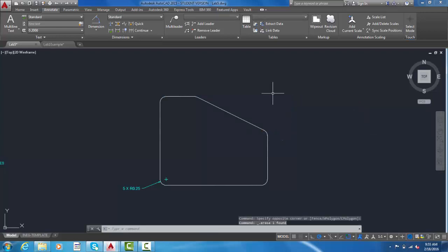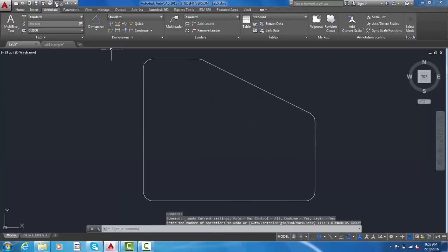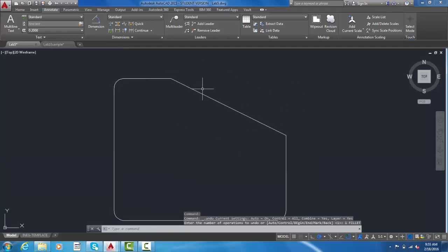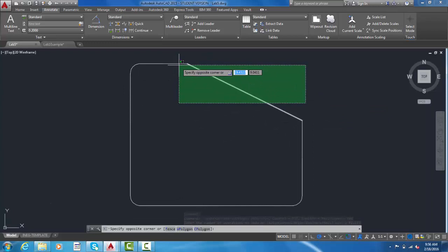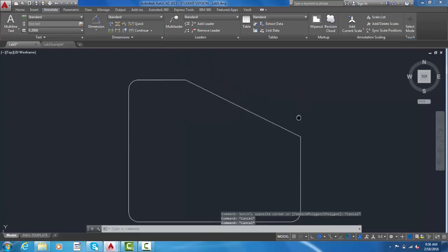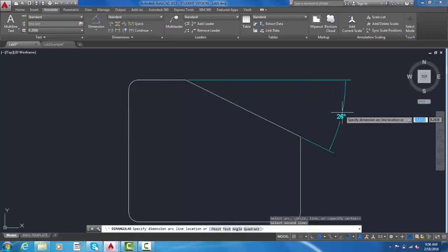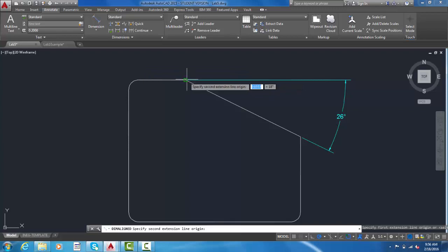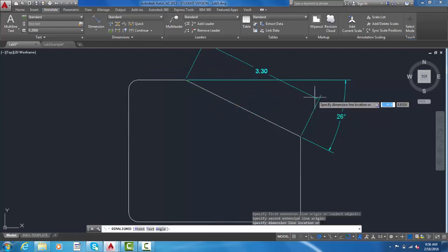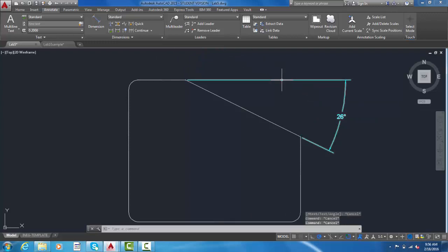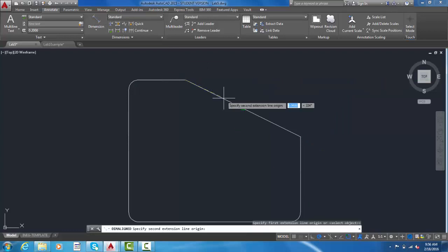Let's go ahead and do this. To discuss that, let me undo a few things. Get back to sharp angles. Right, so here, what we've done is I've taken out the radii here and here. So to make that point, I can dimension it like this. All right. And then I would also have to dimension a length. This would be an aligned dimension. So I could do something like this. Again, bad practice really to have the dimension lines crossing. So this is a case where I would probably go ahead and put in the line dimension